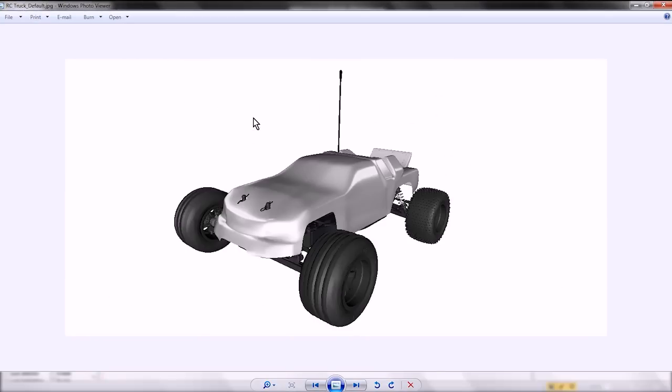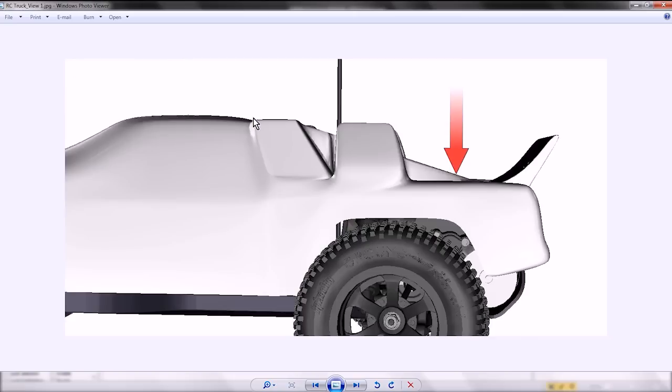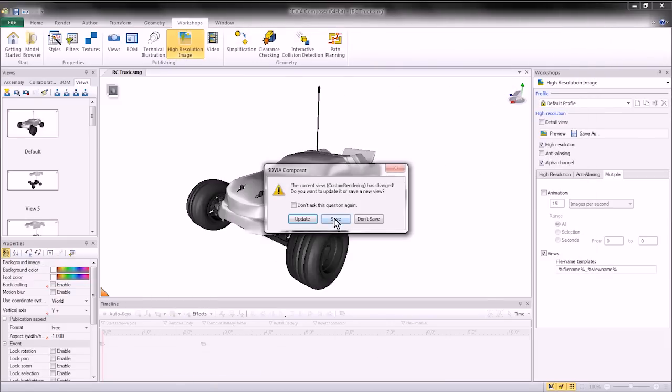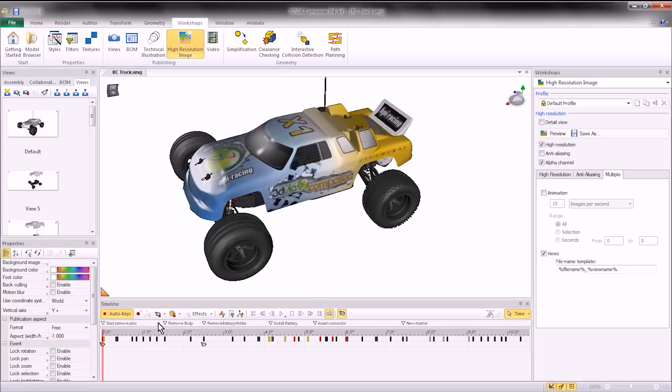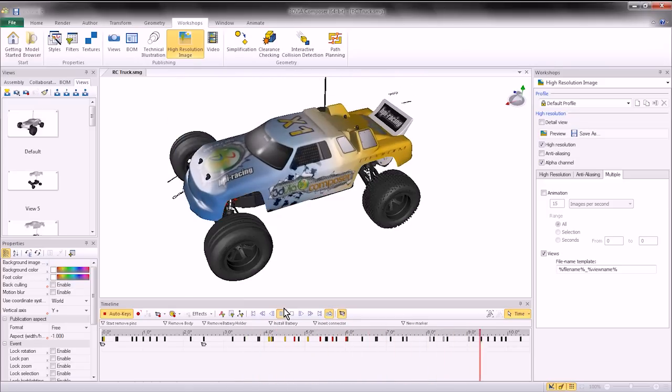So the next time you open up your document, so we can see here, once we jump to one of the images, there we go, one of the images that shows this change, wherever that image shows up inside of our final publication, will then have an updated image, the latest and greatest geometry included. Now this also includes our animation. So we spent quite a bit of time creating an animation, and we have that animation loaded, but without any extra work at all, 3D Via Composer, because it's replaced the geometry directly from the CAD file, is now able to maintain all the animation intact.